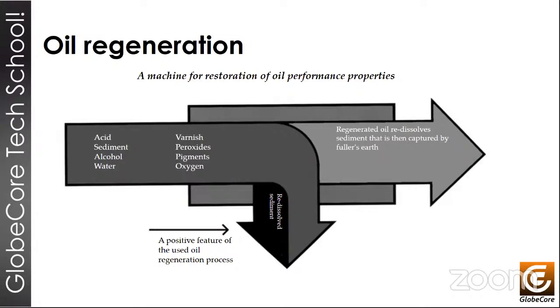And at the end of the oil regeneration process, the oil is basically reset and its parameters are very close to the original oil. What happens is that this process also removes oxidation inhibitors, and therefore, whenever we regenerate oil and we want to maintain the parameters of inhibited oil, then we must add that inhibitor back into the oil at the end of the process. Next slide, please.